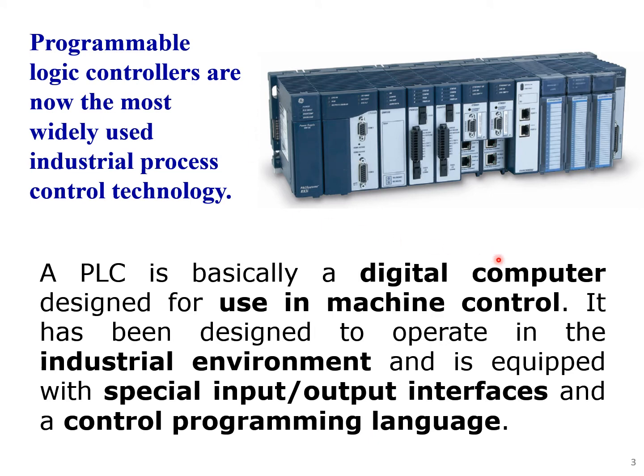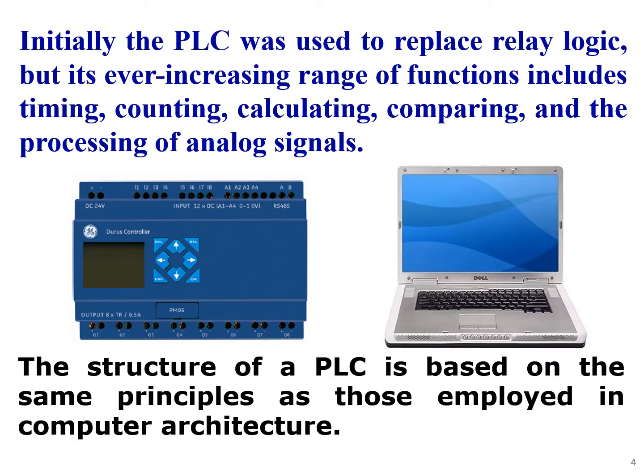So a PLC is nothing more than a digital computer specialized for the industrial environment with specific input-output interfaces. Initially, the PLC was used to replace relay logic, but its ever-increasing range of functions includes timing, counting, calculating, comparing, and the processing of analog signals.